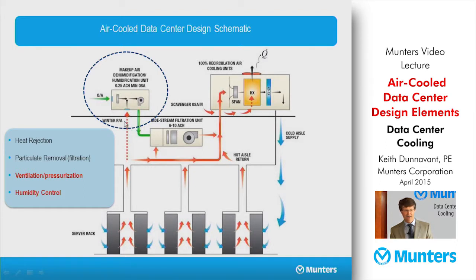So you will see this dashed line here. Now, that is allowing return air to come back to this unit so that you can use heat from the data center to run over evaporative type humidification media so that you can add moisture to humidify without the need to do any heating. You don't need to boil water in a data center to humidify. There's no reason to waste that power. You've got plenty of heat available in a data center. You might as well use it to put it to good use so that you can humidify essentially for free using that warm air over evaporative medium.